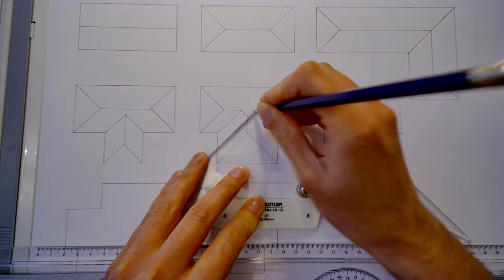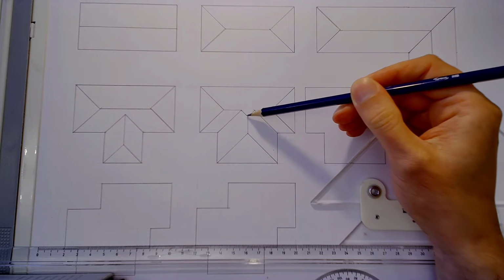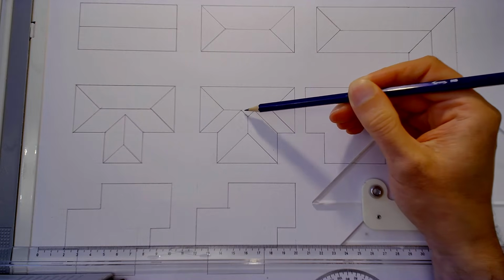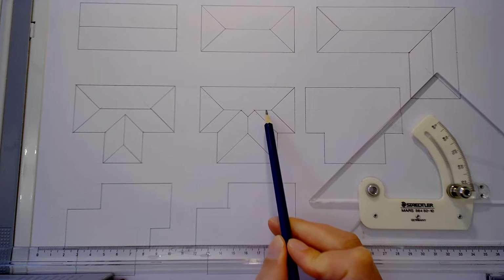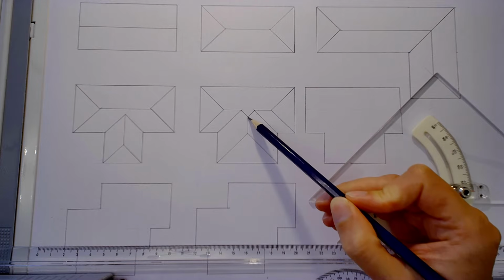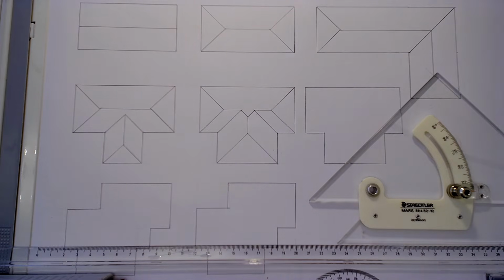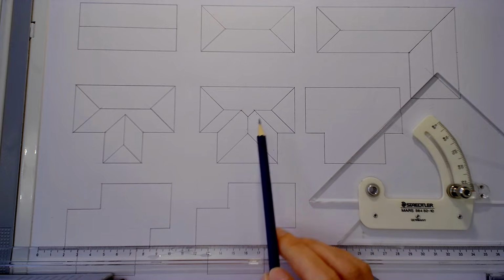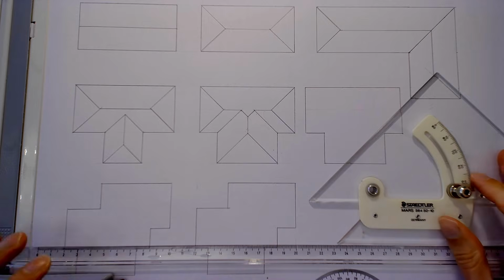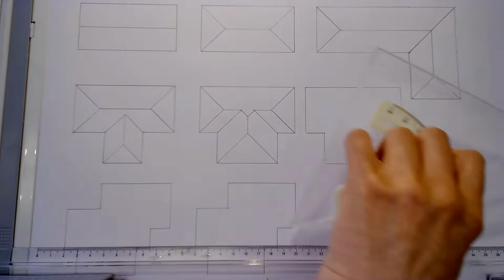So what we've created there is now that roof slopes up here, and it just slopes up a bit higher in that triangular section there. So we've got the ridge coming along, and then we've got a short hip going along here, which is going up until it gets to this ridge, which is now at the highest point of the building. And then those two valleys are by there, and we've got the other hip there. So that is method number one, where basically you're making this the tallest part of the building and these bits are slightly lower.